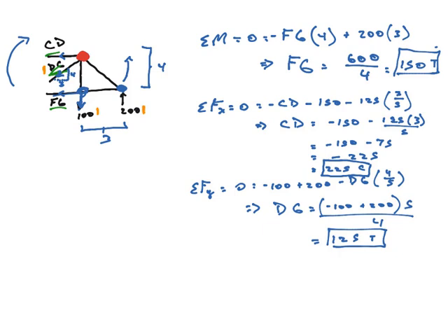And so we can see, even when I guessed the wrong direction, I will still get the right answer. It's just the direction will be wrong, so it'll be negative instead of positive. So don't take the time, at least for method of sections, to try to figure out what you think. It's more difficult than it is when we're trying to find the reactions.